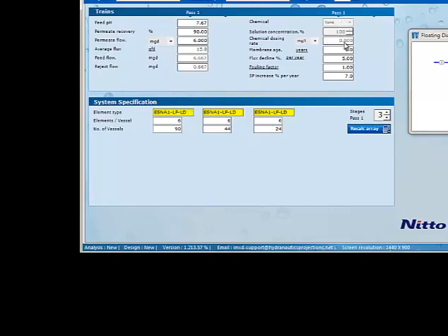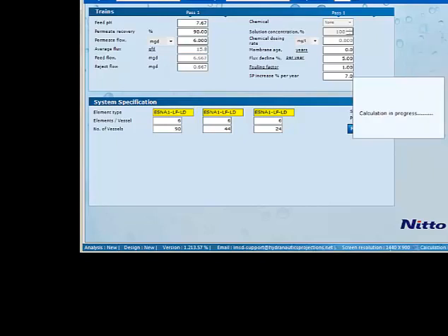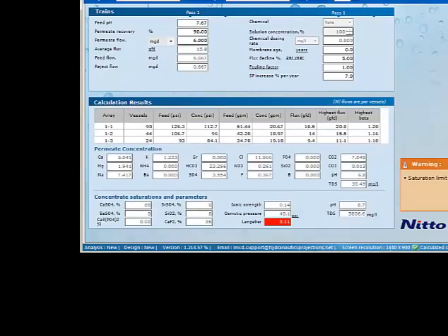And then we've got different chemical additions that we can choose. Look at different dosing. It's going to tell you how much chemicals you want to put into this. So for now, let's just leave this as none. This one doesn't actually use any chemical feed that's there. So now the next step is to hit run, and you'll see this flow diagram came up, but let's run it again just to make sure everything is okay.